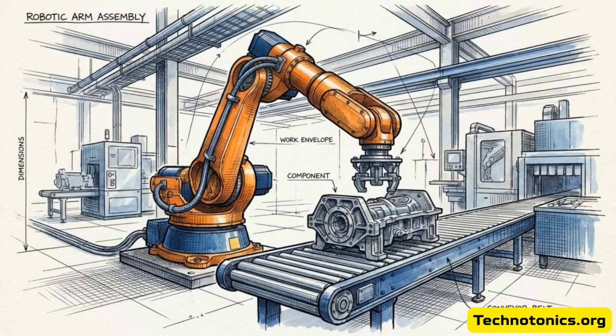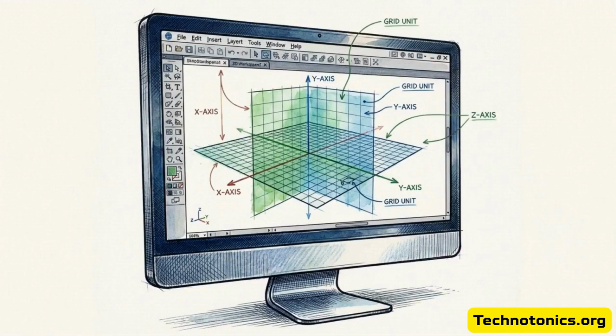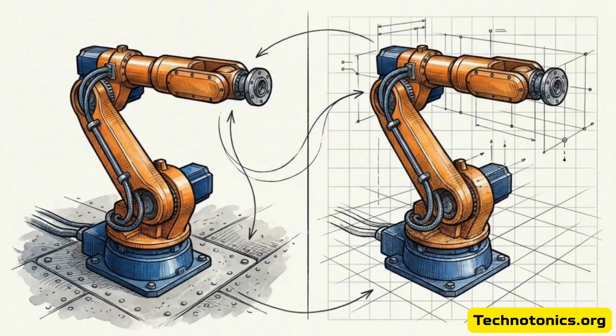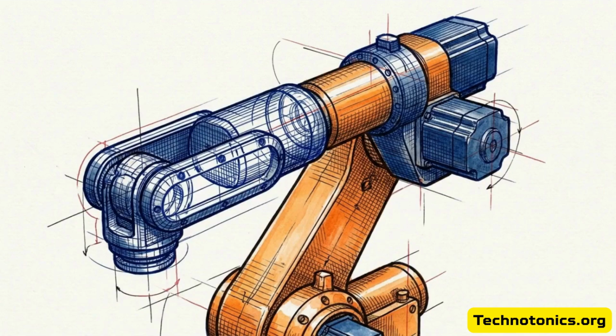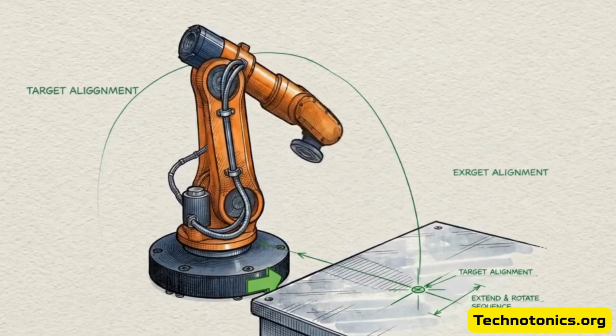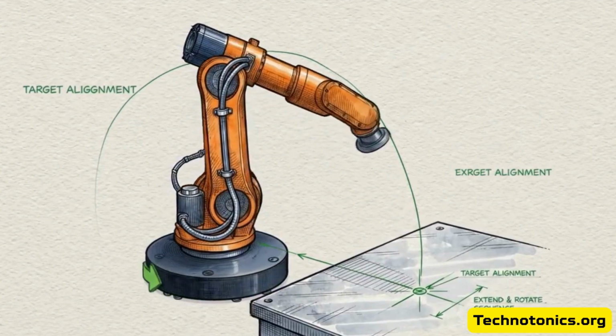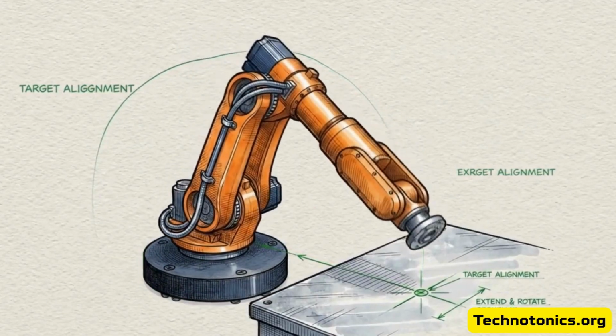Step 1 begins in the RoboDK workspace. This is our control room, where we transition from the physical hardware to its digital twin. We start by running the calibration module. This aligns the digital model so its baseline configuration is an exact mirror of the physical unit standing in your shop. To verify the calibration, run a single test movement. You need to confirm that the coordinates in the software match the real-world coordinates perfectly.